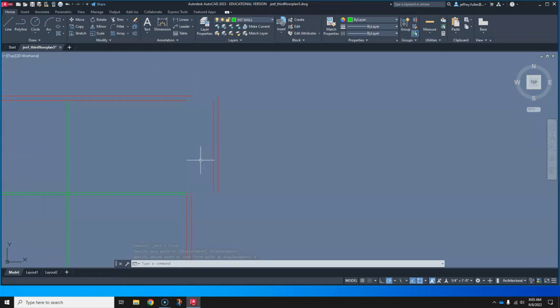I might need to extend it a little bit more. Okay, so 5 feet can make the bathroom. But yeah, I think I do want to extend that more. So let's do that a little bit more. So let's do the move tool again. We're going to select them. We're going to go to the move tool. We're going to come down and just kind of find the center of the wall somewhere and click to make that my base point. And then move. I'm going to add 5 more feet to it, so it's 10 feet. That's going to make a closet space and bathroom space.